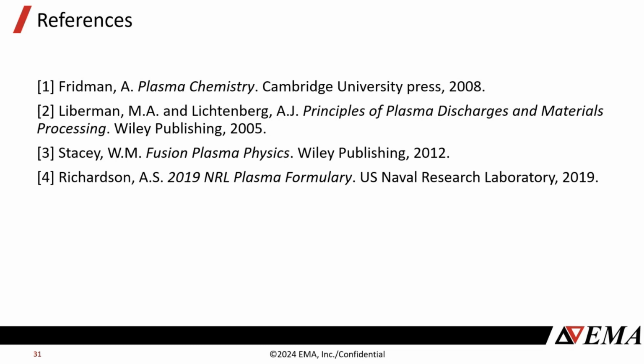In fact, what occurs for vacuum discharges is your electric fields will reach such a high magnitude, usually on the order of like 10^7 volts per meter or somewhere around there, where they can just rip electrons off of the surface of conductors, freeing them from the metal and launching them into space. And so that's how the electrons are produced for vacuum discharges.